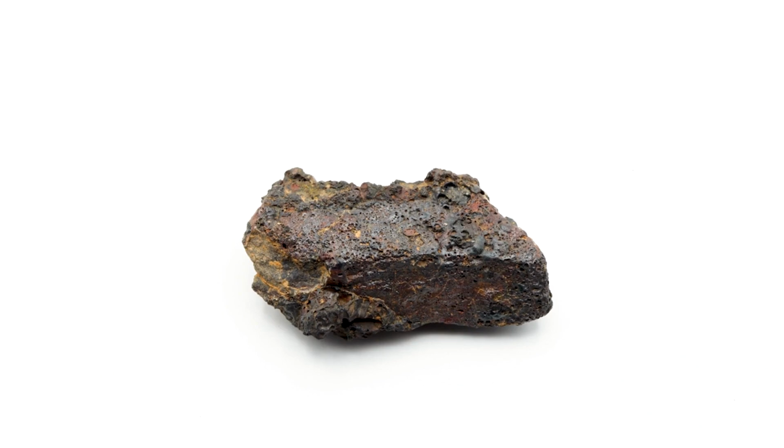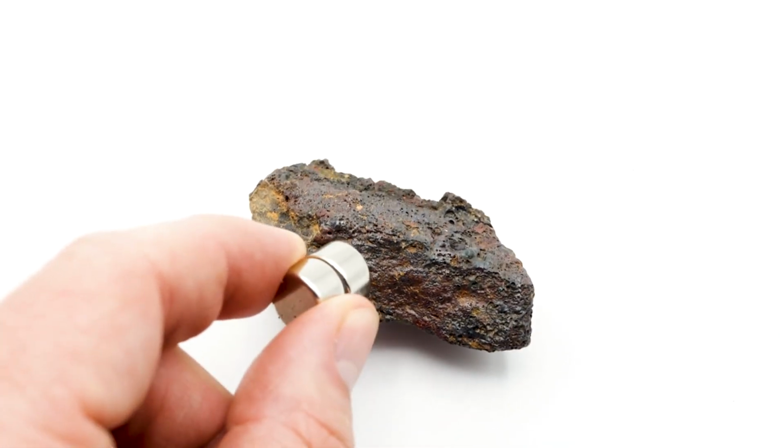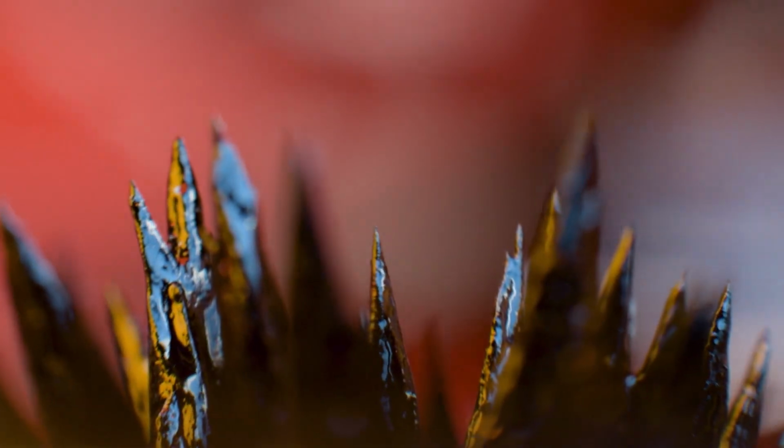Hard iron means that the components remain magnetized for the rest of the vessel's life, or permanent magnetism. Soft iron components do not retain magnetism. They adopt the Earth's magnetic field induced into them while on a particular heading. It is called induced magnetism and can gradually change each time the boat changes course.